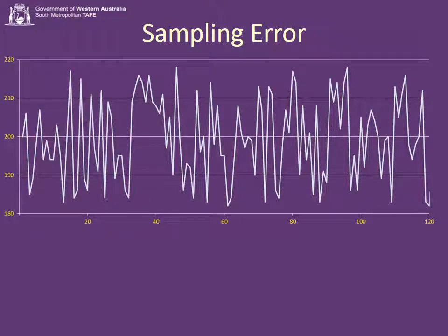Here's another signal. Now this isn't being caused by a fluoro. This is a static air pressure on an air handling unit. Now static air pressure is always unstable, and depending on where you put the static air pressure sensor, it would be more or less unstable.